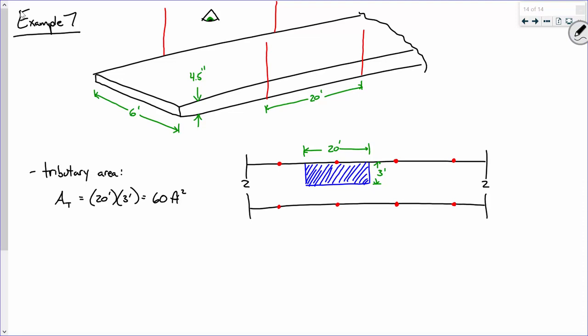Well, ultimately, I'm going to have to factor the load, but what did you say? There you go. It's 100 pounds per square foot applied over a square footage of 60 square foot. So 100 PSF over 60 square foot, you just multiply the two.